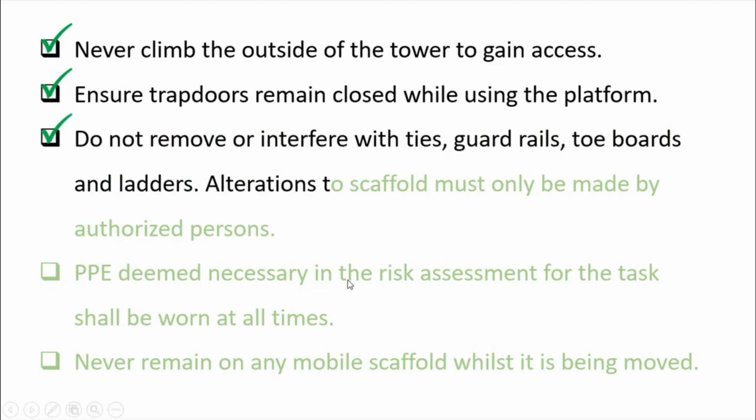Do not remove or interfere with ties, guardrails, toe-boards, and ladder. Alteration to scaffold must only be made by authorized persons. Okay, so you are not allowed to alter your scaffold while you are using it. Coordinate always with the authorized person. So if you are the engineers, you need to make requests for a full-time scaffold person, authorized person.